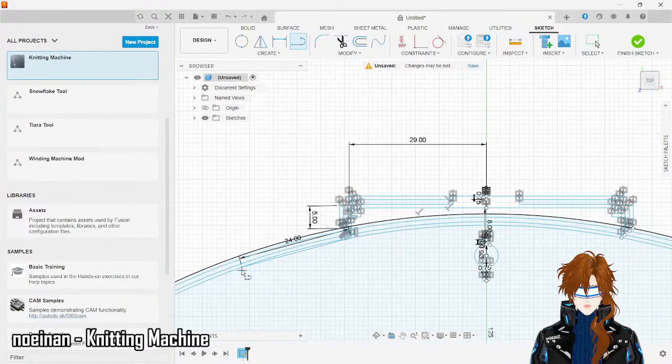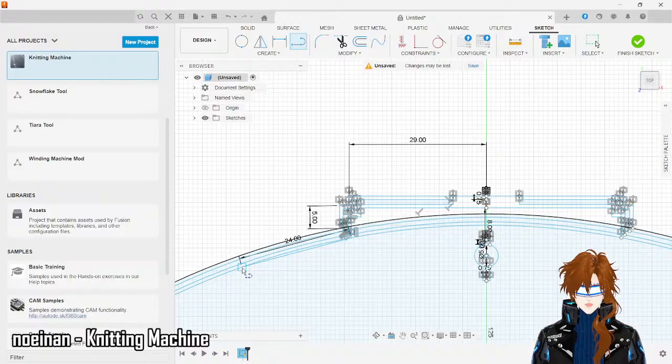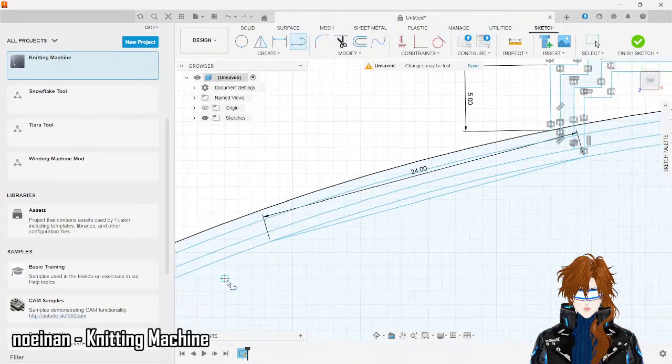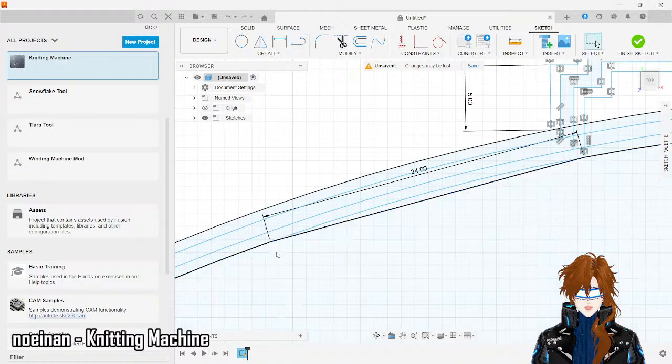And you do want to make sure that the X is there, because if the X isn't there, that means the lines don't intersect and it won't actually form a part, which is a huge pain to correct later if there's just a very tiny amount that isn't there. So this is where our circle starts. And it's gonna go...